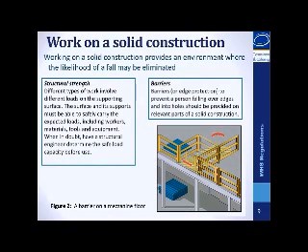Work on a solid construction. Working on a solid construction provides an environment where the likelihood of a fall may be eliminated. A solid construction means an area that is structurally capable of supporting workers, material and other loads applied to it, is provided with barriers around its perimeter and around any openings from or through which a person could fall, has an even, accessible surface and gradient, and also has safe means of entry and exit.